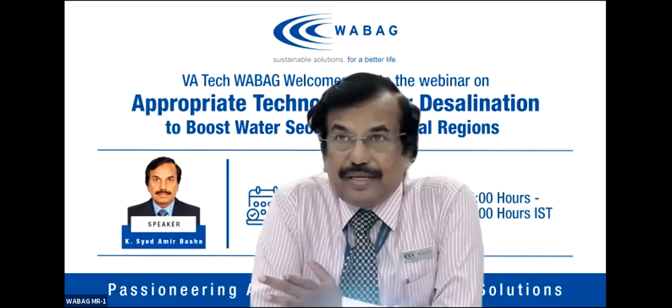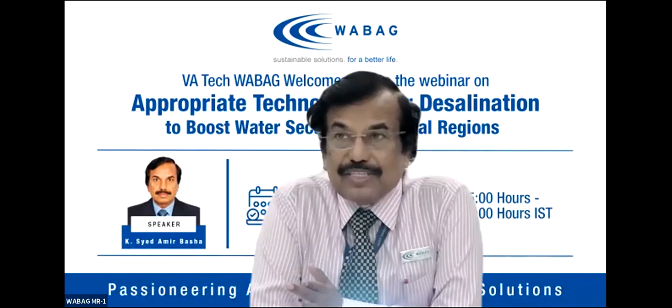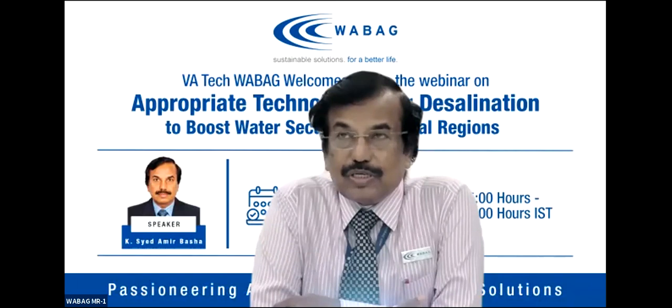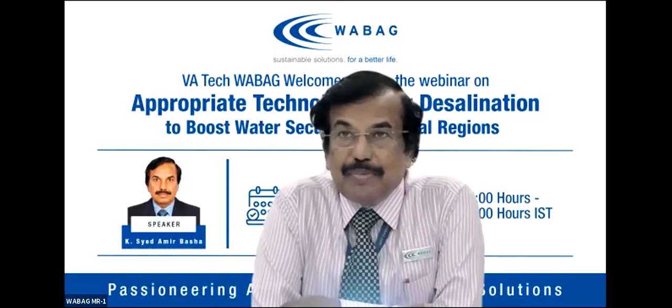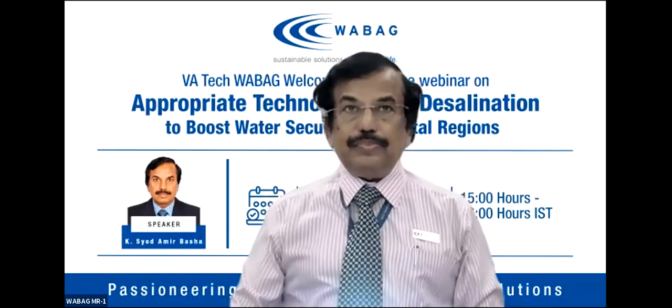But anyhow, today, seawater reverse osmosis is the standalone process which is cheapest and which can go for a high capacity like the 300 or 400,000 meter cube per day. Yes, maybe another 5 years you will have membranes operating with lesser pressure than 50 bar and specific power consumption less than maybe 2 kilowatt hour per meter cube.